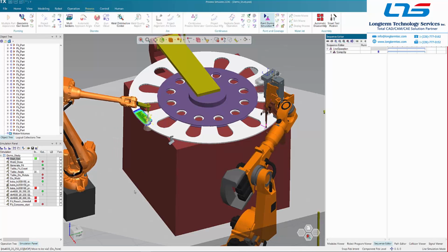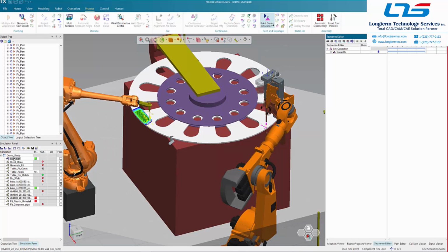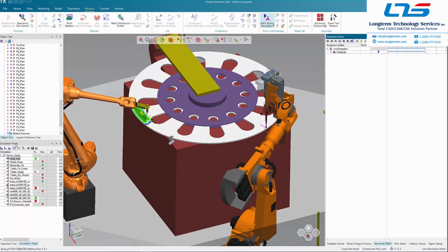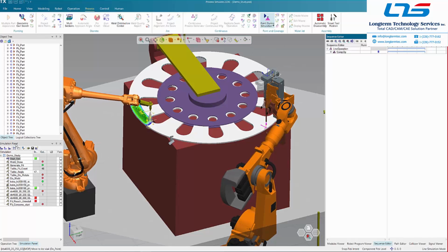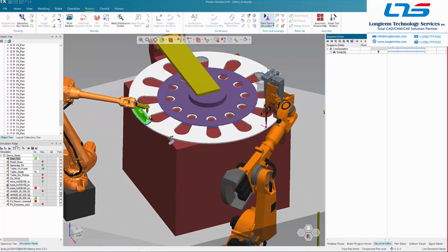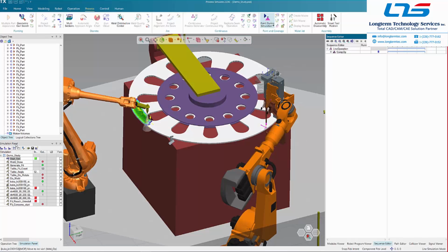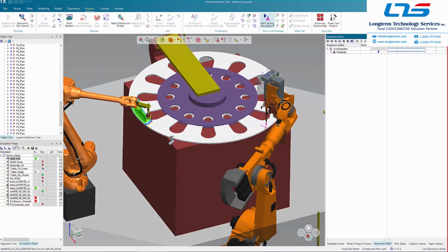on the left-hand side, there is a simulation panel. That is really up to you. You can pick a couple of signals. You can also monitor the signal status here. So sometimes this is a very handy feature that you can debug. You can manually control some signals from here to test your robot cell. So yeah, that's the process.